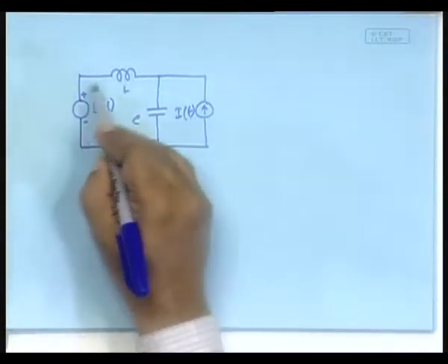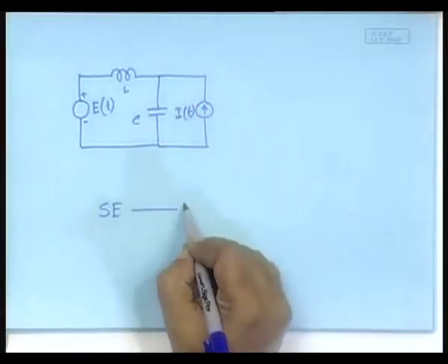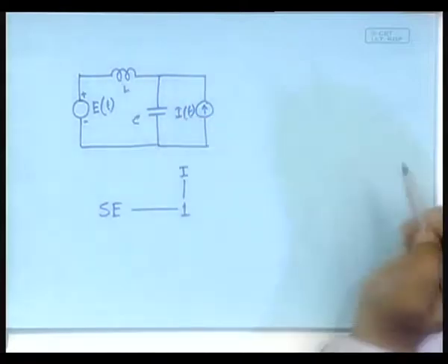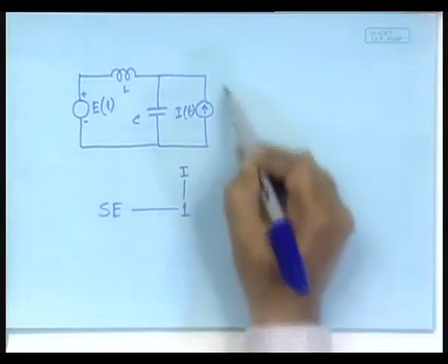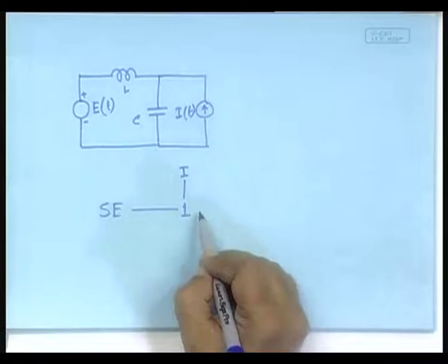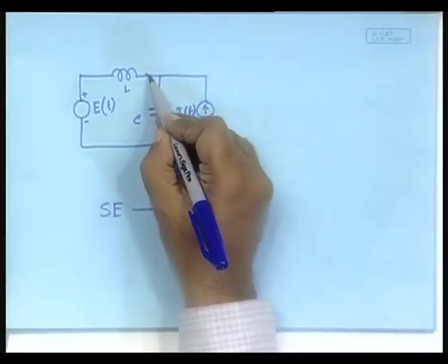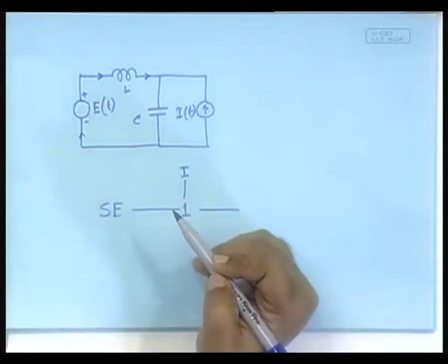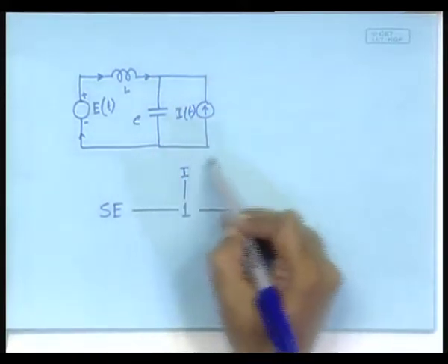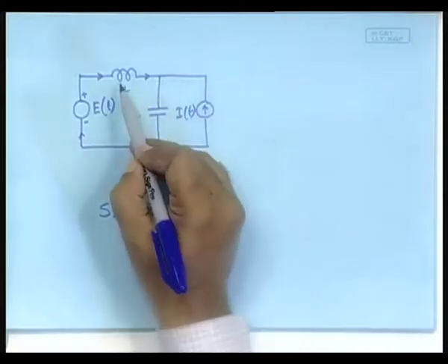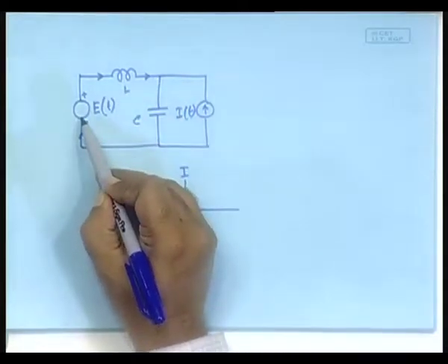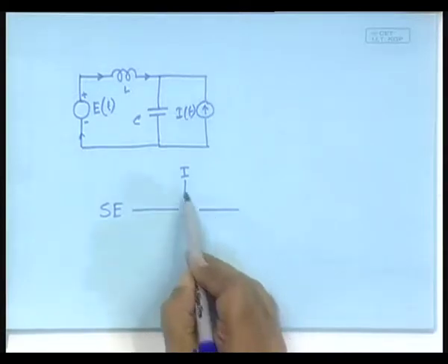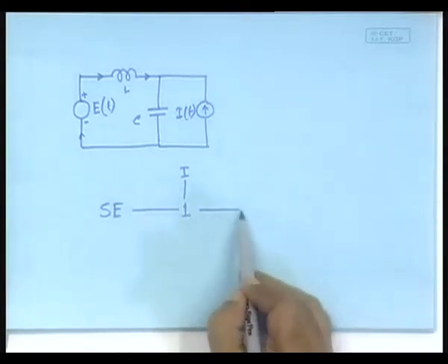Therefore, it should be connected to a one junction to which the I is connected, and the rest of the circuit, this whole thing also shares the same flow, right. The flow here and the flow here and the flow here are the same. So, this whole block shares the same flow with the inductor and the source of effort, and therefore, this is the representation.